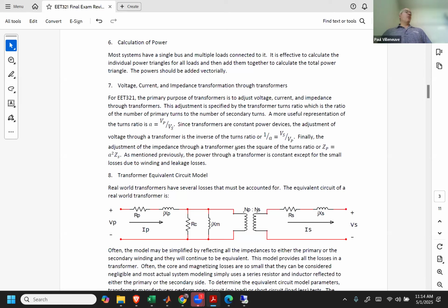When you have impedances on one side of a transformer and you're trying to get the equivalent of that impedance on the other side of the transformer, you need to reflect that by either the turns ratio squared multiplication or division by the turns ratio squared. And that's how you can move things along. It's a good thing because, as we talked about, our house maybe looks like a 10 ohm resistor, but from the utility perspective, we look like a 7,000 ohm resistor. So we're not drawing lots and lots of current at whatever the utility voltage is. So it makes our system, again, very efficient, and we can deliver all the power we need.